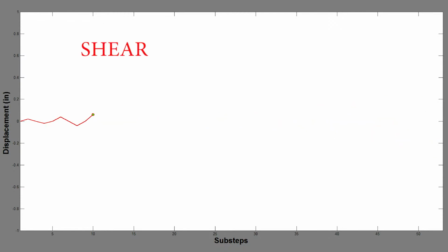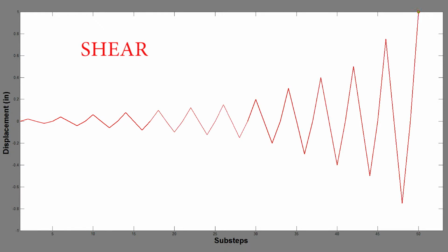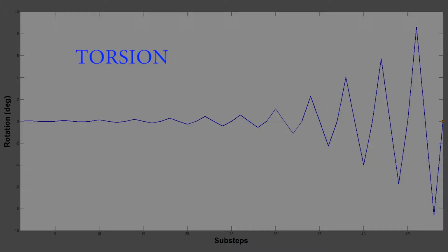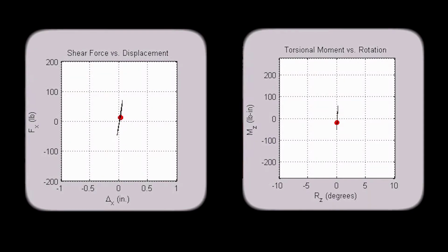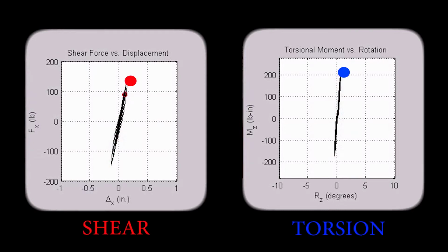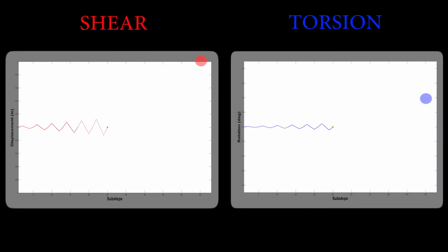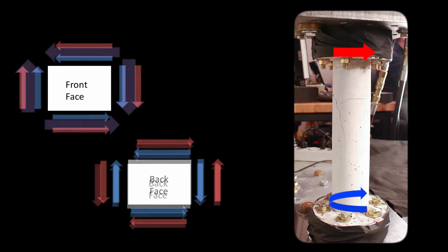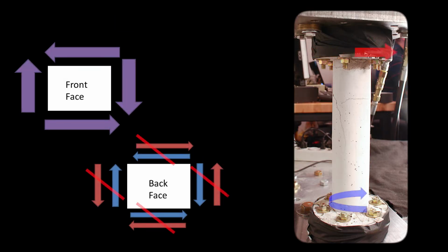The shear case imposes displacements ramping up to 1 inch or 25 millimeters. The peak rotation applied is approximately 9 degrees. The displacement and rotation reached while maintaining linear elastic behavior are noted. The linear elastic results from the shear and pure torsion cases were used to scale the levels of applied loading for combined loading cases where the interaction between shear and torsion were demonstrated.